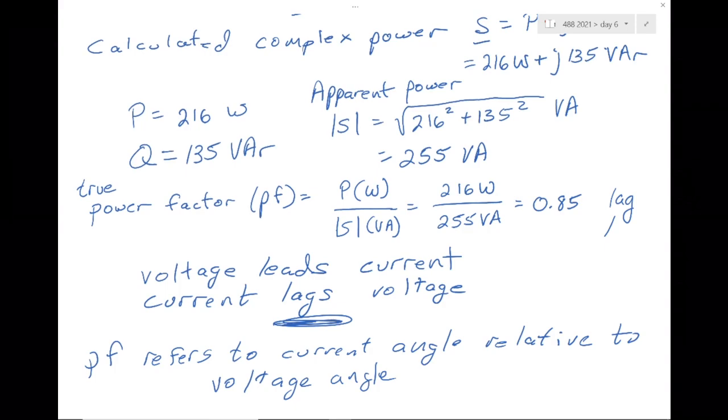However, I tested several single-phase induction motors that I have around my home. The rest were all fans, and they had power factors right around 1, which I was surprised to see because induction motor power factors are usually pretty low, 0.7, 0.75.